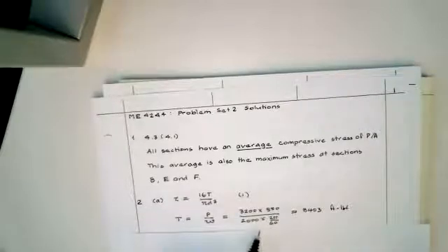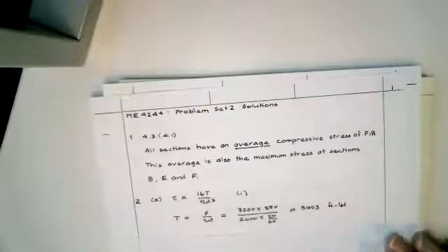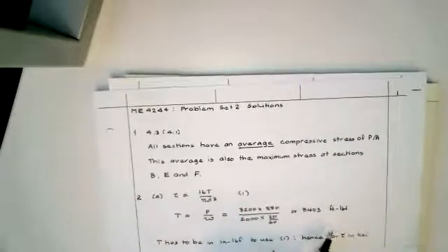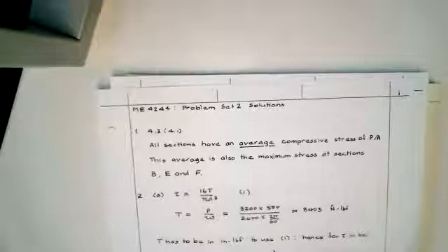This was given in RPM. You want to make these radians per second, and so it's 2 pi and 60 seconds. That'll be radians per second. And that gives you the foot-pound force. To use that in the stress formula, you've got to make it inch-pound force. In mechanical engineering, we usually give torques in foot-pounds force. But if you want to use them for stress analysis, you've got to multiply by 12. And when you do that, you get the following. I did this in KSI.